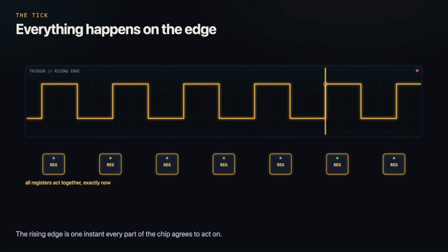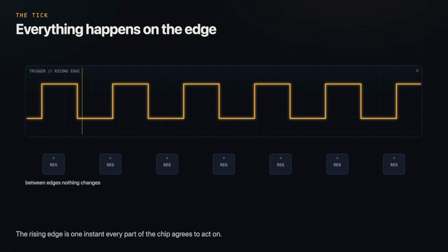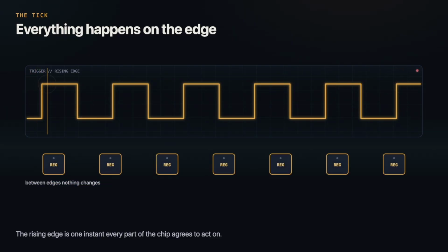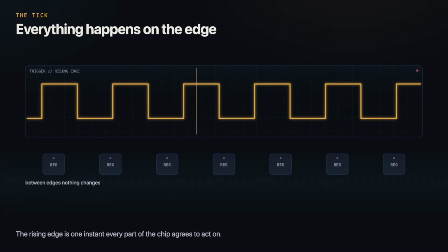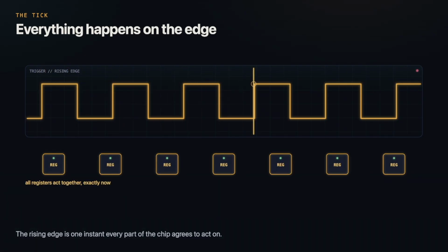Because the rising edge is the moment that matters. Synchronous chips are built to act only on that edge, the instant the clock snaps from 0 to 1. Between edges, the clock holds still and the circuits are free to settle. Then the edge arrives, and every part acts at once, on the same tick. The edge is the shared now that the gates were missing.